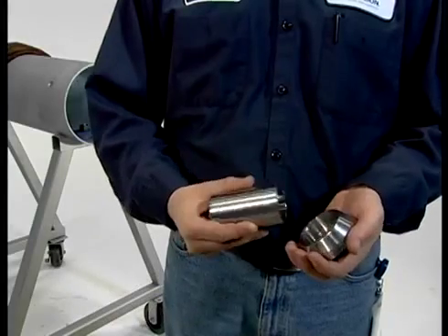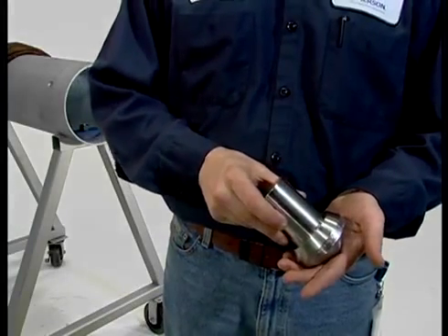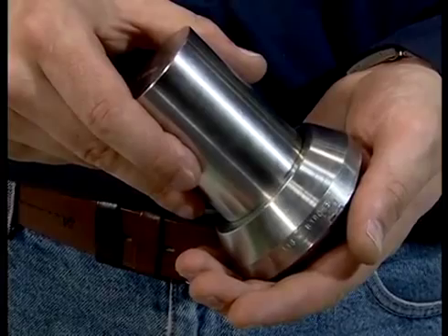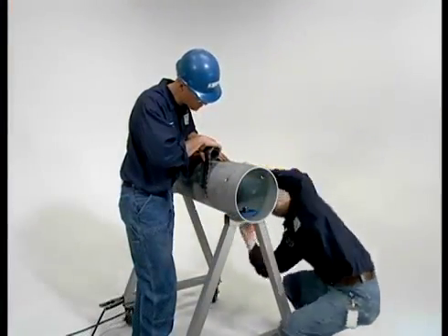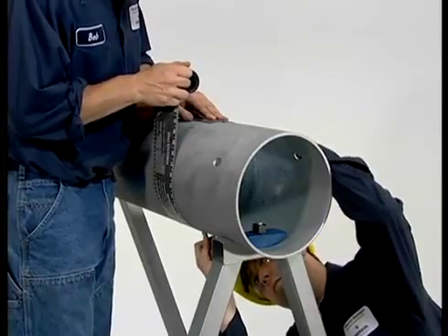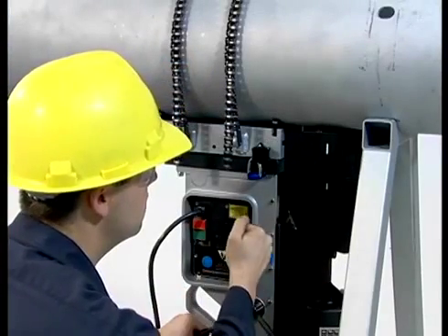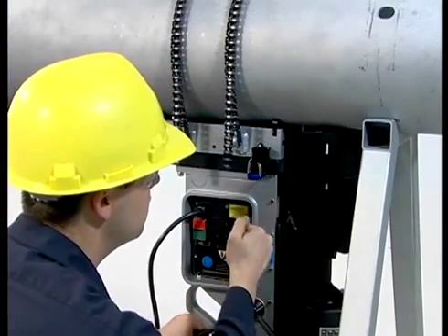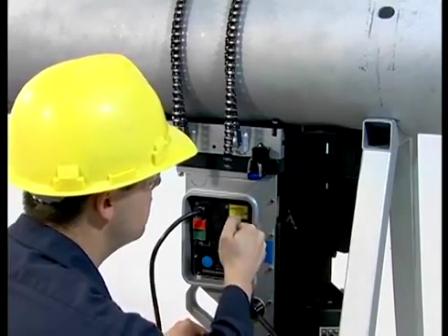Some flange assemblies require an opposite side support that is mounted 180 degrees from the original hole. Use a pipe tape to find this location and then mark it. Next, drill a hole that is exactly the same size as the one on the other side of the pipe.